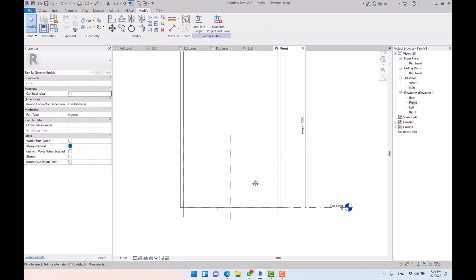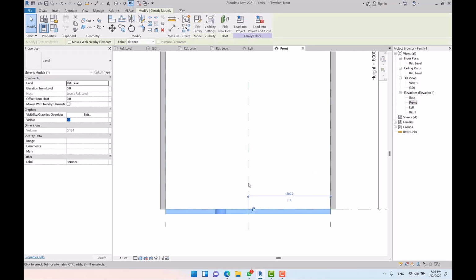Very well. Another example is creating chandeliers: creating the branches of the chandelier, then loading them there as a nested family. We can model the main part and then the branches separately, and then we can load the branches there and then duplicate them. For example, about modeling doors, we only create the frame of the door. Other parts of the door, for example the handles and the panels, are considered nested families, since these families should be moved with each other. Now, there are too many cases that can be exemplified.